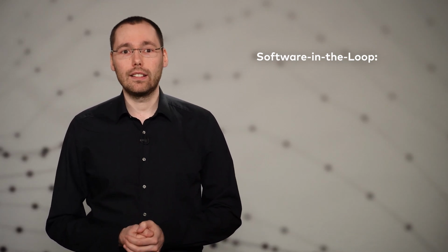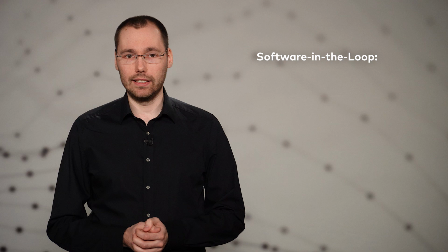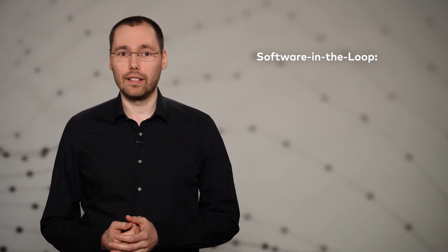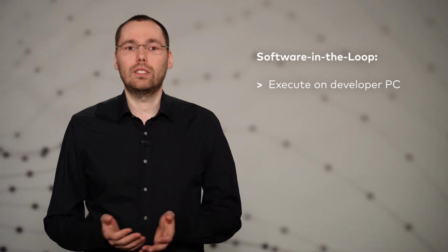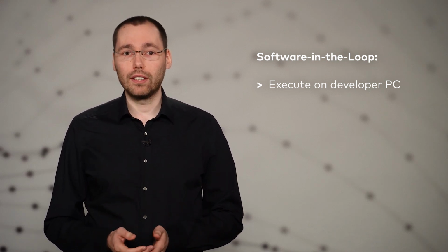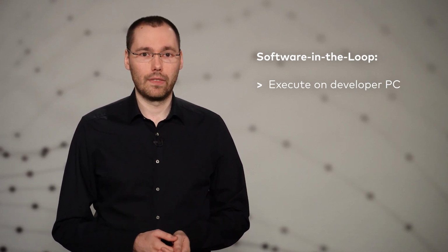Instead, we can use them much earlier during development, even if we do not have any hardware available yet. This approach is called software-in-the-loop testing, or SIL. SIL is a simulation-based testing technique where the embedded software is executed on a host machine, typically the developer's computer, rather than on the target hardware.